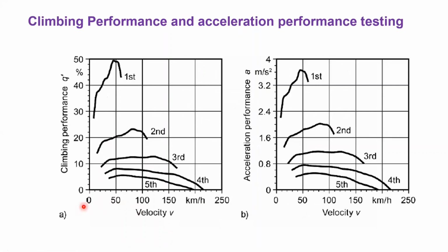And when the vehicle is going up hill, say for example when you have a gradient, for which you normally run the vehicle in the first gear, and this also depends on the angle of the hill or the gradient, and accordingly you need to select the gears as well. And again, you also have the acceleration corresponding to the gradient. For a normal road you need to have high acceleration, and you can run up to the fourth gear or fifth gear or sixth gear, whatever it is. But when you're climbing the hill, you need to have more torque at the initial stage. Accordingly, you need to select the gears basically.